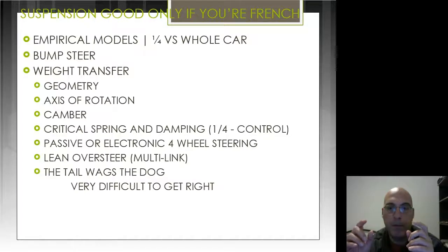So a lot of people have now started playing with the bump stops. When the car leans a lot, so you are close to the limit, they will have the rear bump stops. Remember what we said in the first slide with the weight transfer. They'll have the rear bump stops stop first, and that will transfer so, as the car has a tendency to understeer, to make it more stable, more easy to drive.